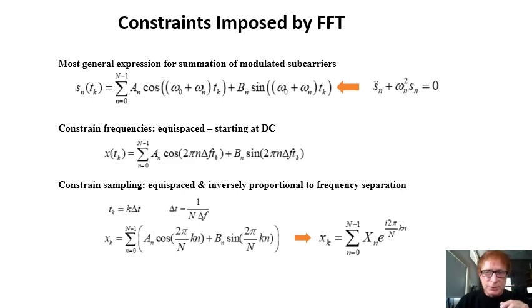The middle equation is a Fourier series representation that begins at a zero frequency, or DC, and must have evenly spaced frequencies. The closed form solution for A and B is what motivates the equally spaced frequencies. But the digital sample rate can be selected arbitrarily. It only requires a rate much faster than the highest frequency or the bandwidth of our signal.